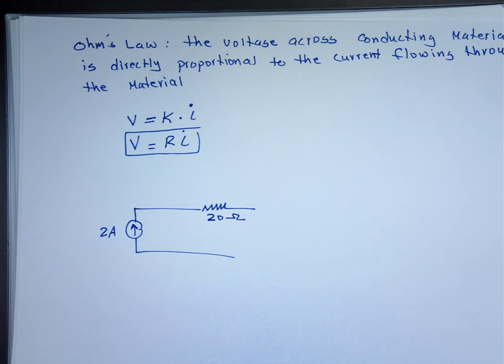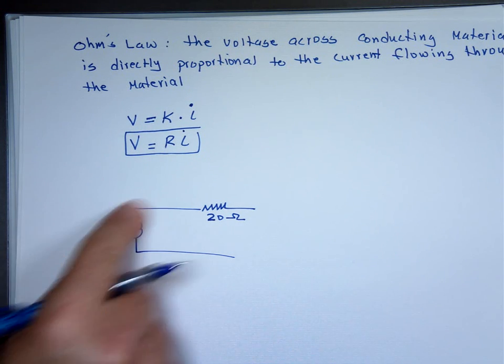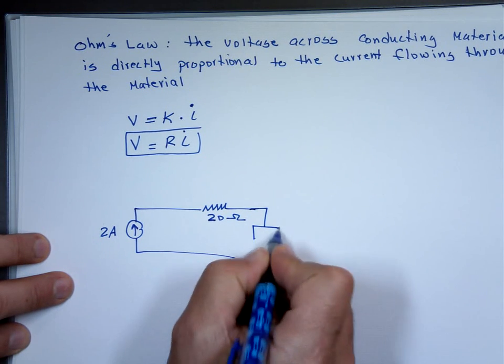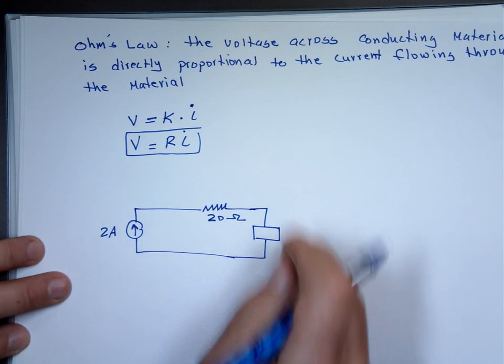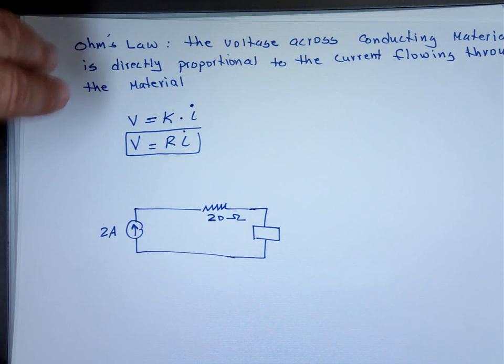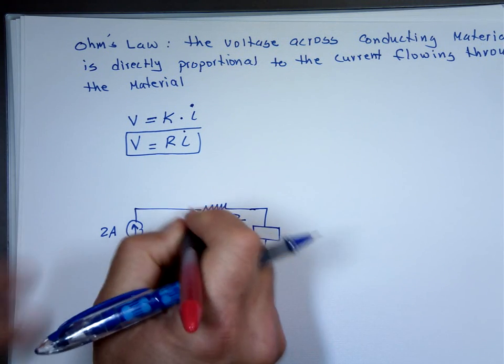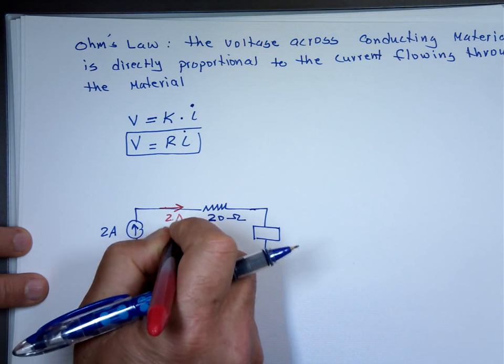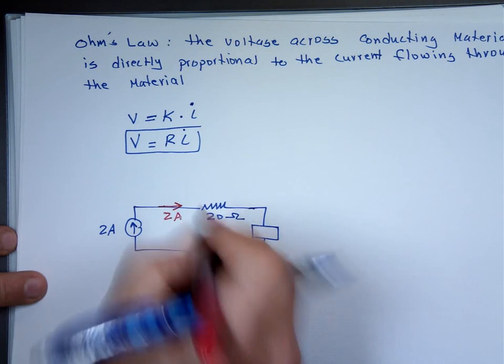That current is going to come down through that resistor. Assume there's other elements here. Maybe there's an element here. That current is going to come down traveling this way. The only current in the circuit is this one. So that means I have a current entering, traveling in this direction, of 2 amps. And as current enters the resistor, it will mark it plus to minus.